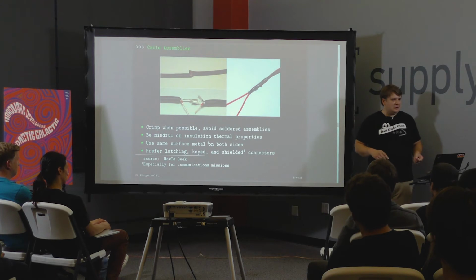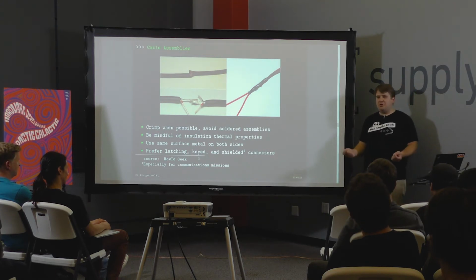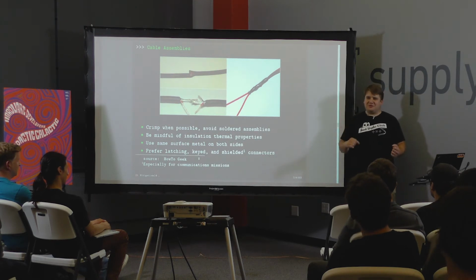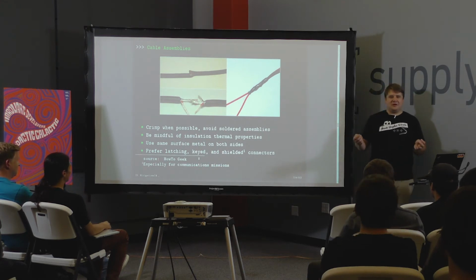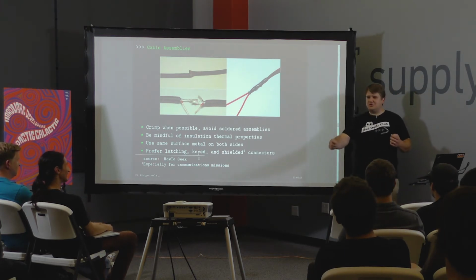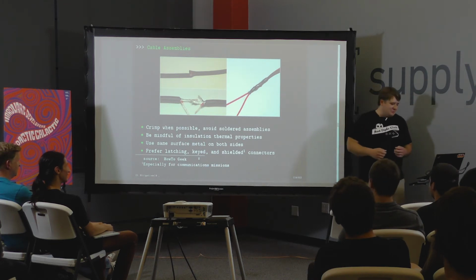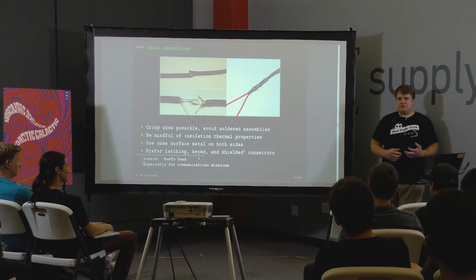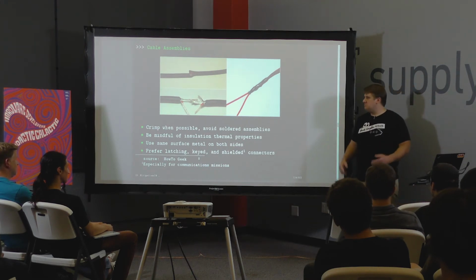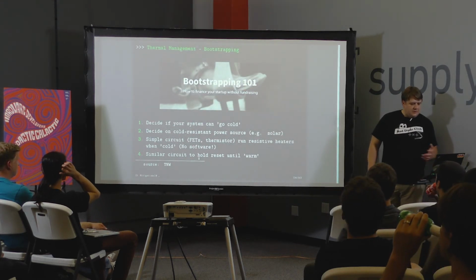Also, we found this out too. You want to have latching and keyed connectors, because again, you're going to have people helping you out. You want to make sure they can only plug things in one way. And also sometimes you're going to be super tired, it's dark, it's cold, your hands are freezing, and you can't see what you're doing. So even if you're the expert on this stuff, you will make a mistake. So be mindful of that. And then if you're doing communication stuff, and again, back to EMC, shielded connectors will save you a lot of trouble down the road because they'll help you keep all the radiation in and solve some obscure issues. And then thermal management.